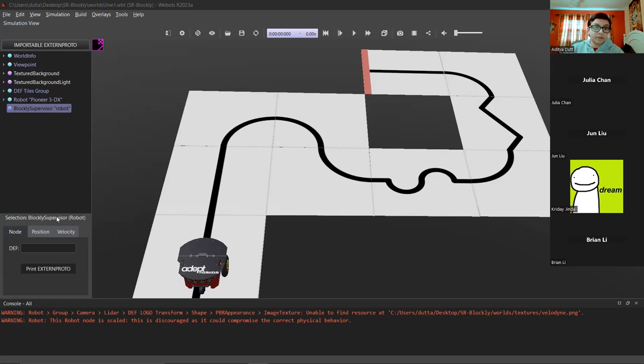These are some of the custom blocks that we added. There's a motor category, so students can interface with the motors on the robots, set their velocity and get their encoder values. We have some time blocks, so you can delay, get the current timestamp of the world, reset the time, and step your robot step by step through those 32 millisecond time steps I was talking about.